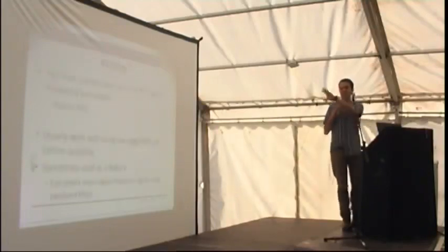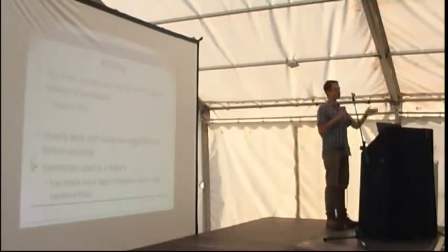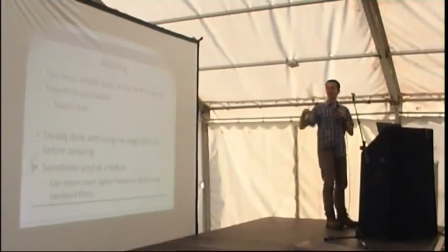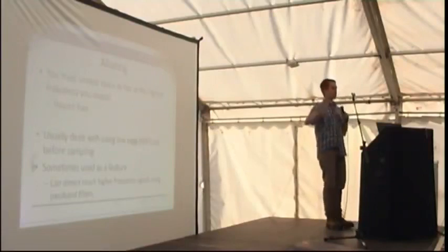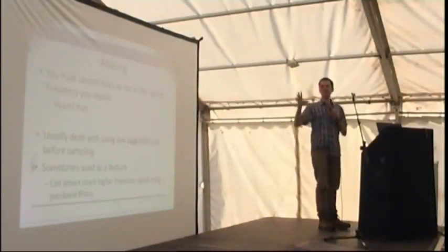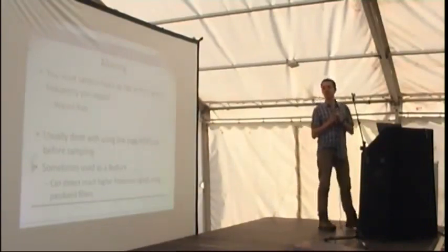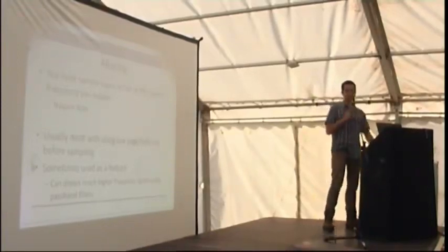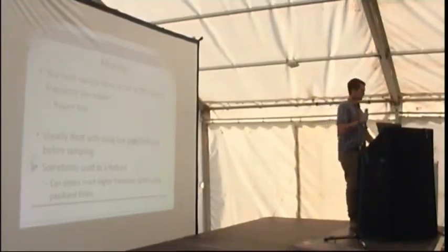So this is called aliasing, and you have to sample at least twice as fast as what you're expecting to receive. Generally what they do is put in a great big filter that enforces this rule, and that way you're no longer going, it might be, it might not be. You know that what you're receiving is going to obey this law. So you have to be sampling fast enough to receive whatever signal you're interested in.